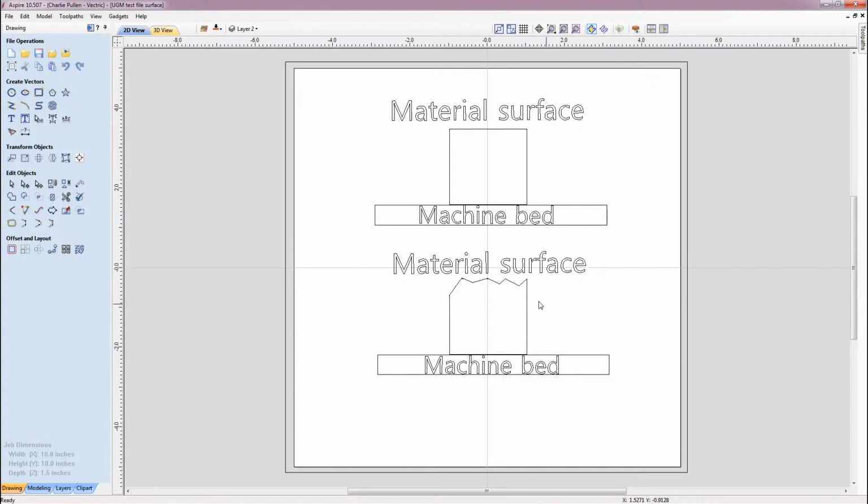but you may encounter some scenarios where the top of your surface is not flat. So you may encounter something like this, perhaps not as exaggerated as this material here, but this is just for demonstration purposes. Now what's the danger with this? Well, what can happen here is you can get an inaccurate cut for one, but also if you have a rapid Z movement with your tool and it runs into material, like for example this peak here where I did not expect material to be there, you could actually end up damaging your tool, damaging the material, and getting a rough cut overall. Similarly, you could end up just cutting air, quote unquote, where the tool expects material to be, but unfortunately there is no material here, as you can see in this valley here.